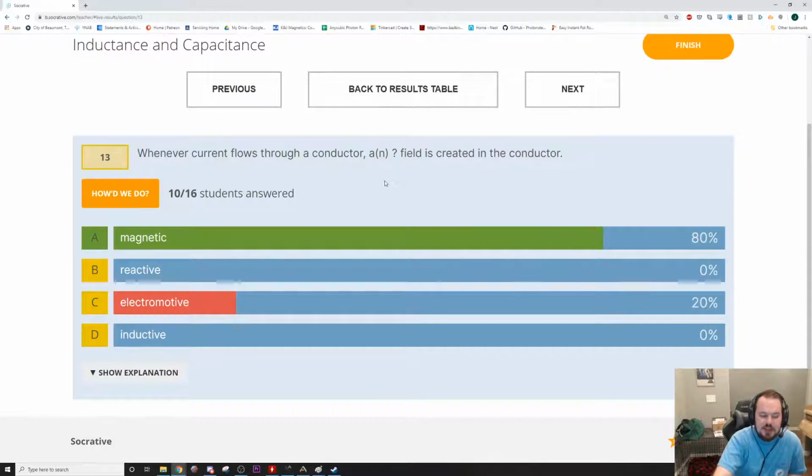Yeah, you can see that. That's how a no contact voltage tester works. It picks up the magnetic field around a conductor. Also, a clamp-on ammeter works the same way. They read the intensity of the magnetic field around a wire.